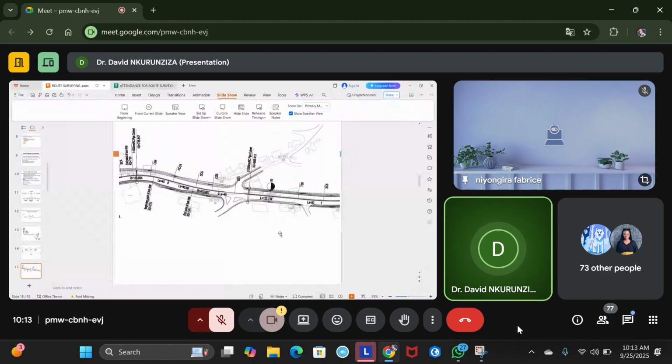This plan view is trying to show us the plan view of a road section where we have a longitudinal profile. The longitudinal profile is passing through here. Through here. This is the longitudinal profile. It is along the length. You can see, for example, if you look here, you have a pipe culvert. This is a culvert to drain water. This is another pipe culvert to drain water here. You see? And then here I've got some nearby houses. So you can see the chainages, PCC4, and so on.